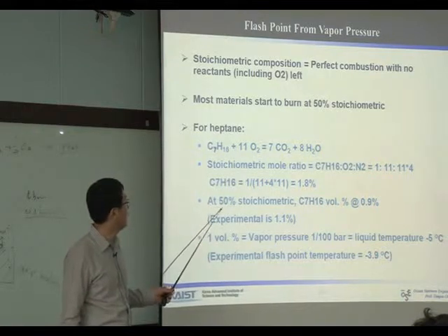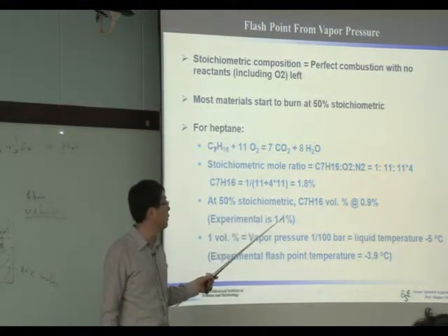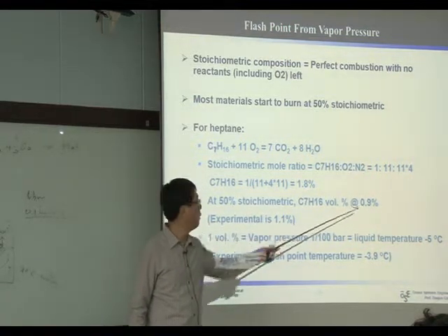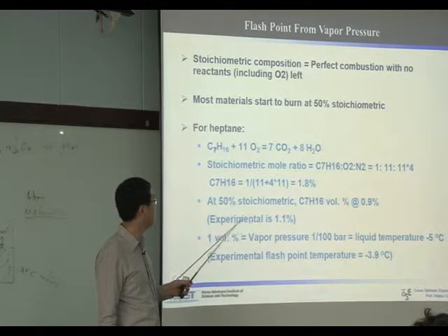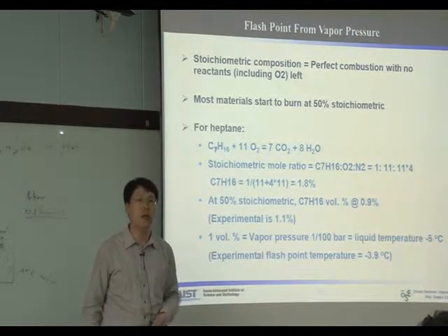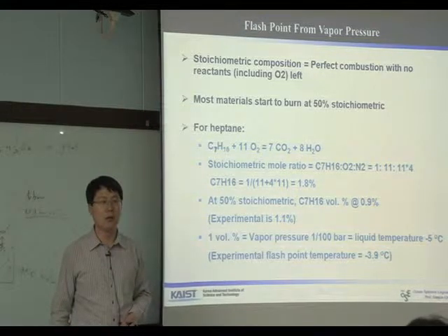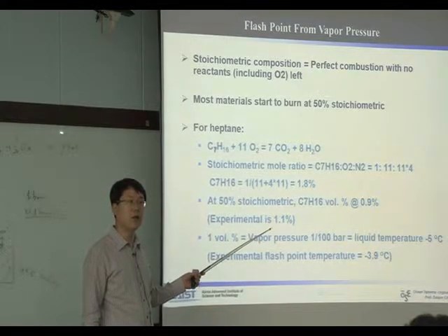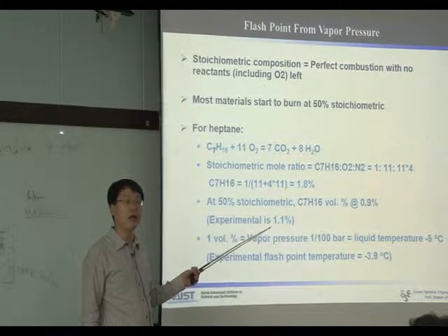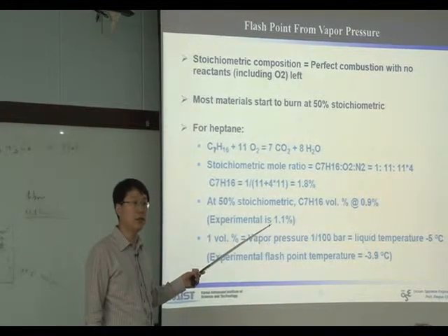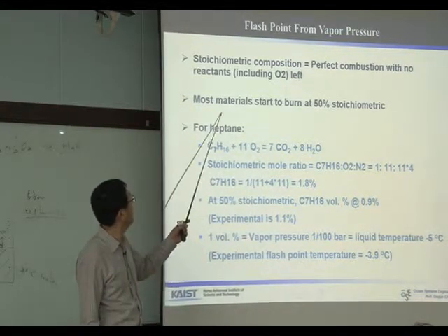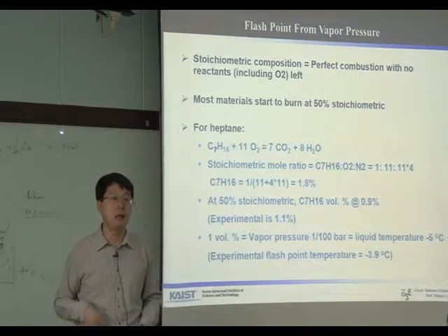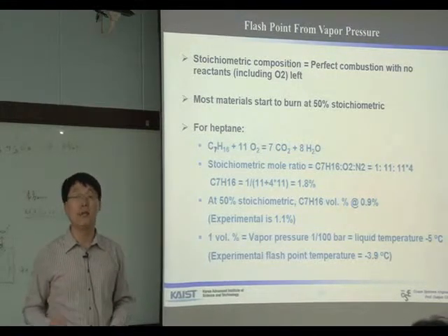At 50% of the stoichiometric concentration, that means 0.9%. But the experimental value is just 1.1. So what is 1.1? This is the LEL, LFL, lower flammable limit. Most materials start to burn. Start to burn means it's LEL, lower explosion limit or lower flammable limit.